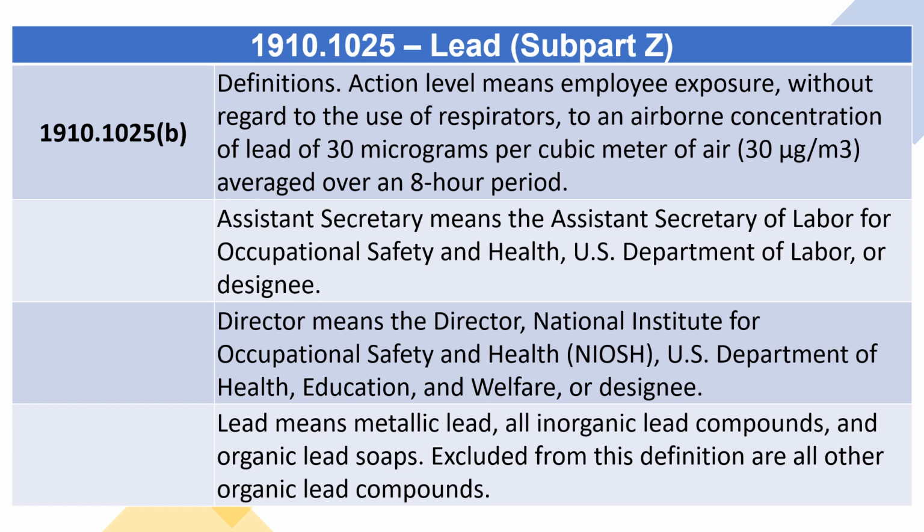1910.1025. B. Definitions. Action level means employee exposure, without regard to the use of respirators, to an airborne concentration of lead of 30 micrograms per cubic meter of air, averaged over an 8-hour period. Assistant Secretary means the Assistant Secretary of Labor for Occupational Safety and Health, U.S. Department of Labor, or designee.